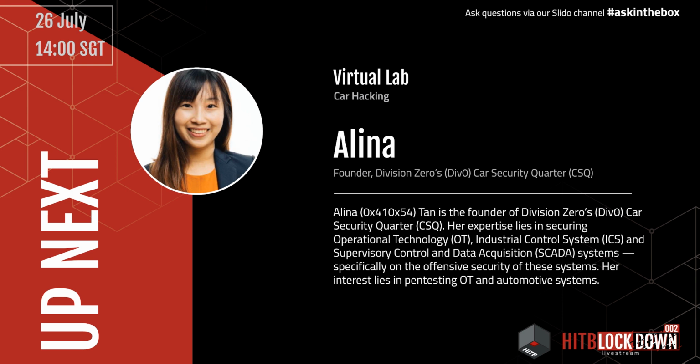How would you tap into the CAN traffic? One example that we learned from our current test bench itself is that, funnily enough, we couldn't draw any CAN messages from the OBD2 port. The manufacturer blocked most of the CAN messages from the OBD2 port, and we couldn't interact with the car from that.